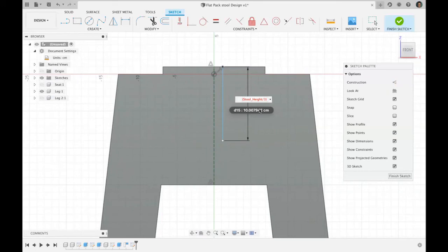And then we need to also add in the wood thickness, the top part, wood thickness, and our bracket. And then I want that line to be just right in the middle of the distance from the top here to the underneath part here. So I'm going to divide that by 2. I'm going to press enter, and it will automatically adjust the length of that line.